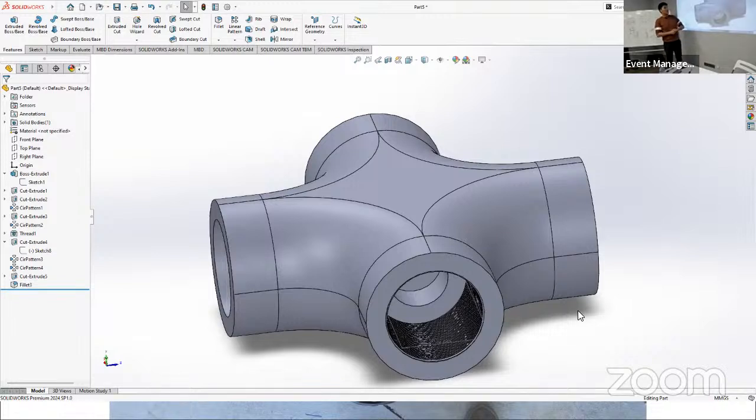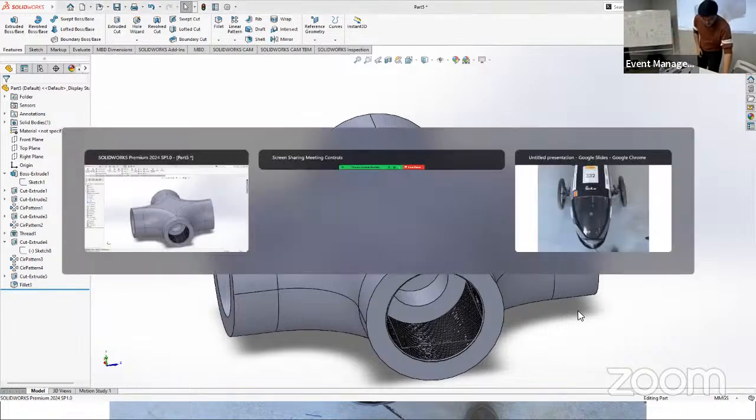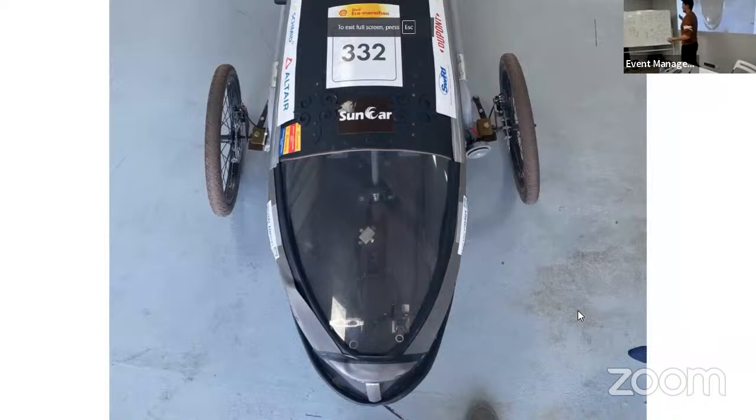And also after we cut all the holes, when it was just a block of metal, you could call it a day, but we also considered how we can optimize it for our needs. In our case, it was weight reduction. That's also one of the aspects of engineering, I would say. After all that beautiful 3D model, what we ended up doing was just a block. I manufactured it by myself, and I didn't have access to CNC machinery. That's why I thought, okay, a block is going to be okay, because just making it rounder will save us only a few grams, which is like a driver who drinks less, maybe.